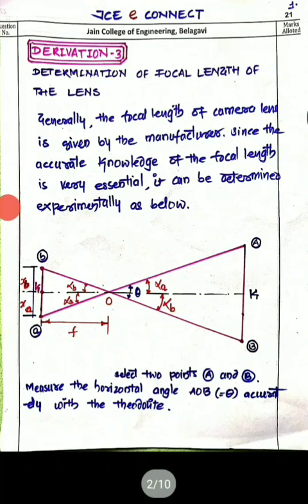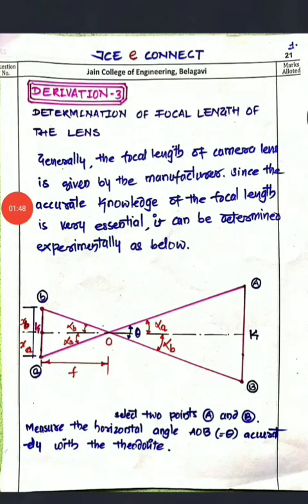This figure will give you the details about the real objects on the ground and the negative. You can see capital AB on the ground, and the negative will have small ab in the reverse manner. Here you will have two objects, object A and object B. You will set the theodolite on the exposure station O, or theodolite station, or you can call it the photo theodolite station.